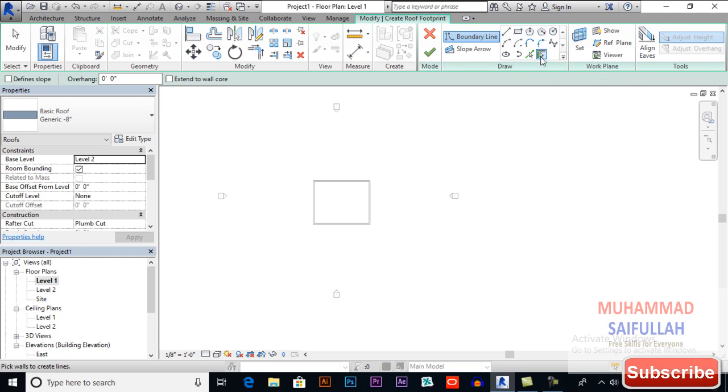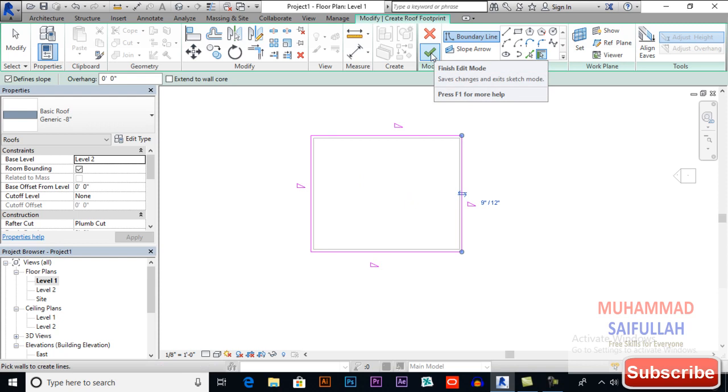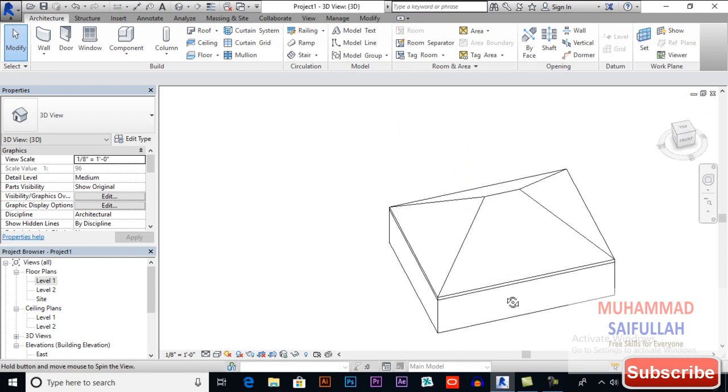These are very simple. Pick walls, and now in the options bar you can define slopes to each side of your roof. For example, I am defining slope here to all sides, and later we will discuss overhang. You also can change its ratio, the slope ratio of a roof. I selected 4 walls, and here we have to finish edit mode. Switch to 3D view to see how it works.